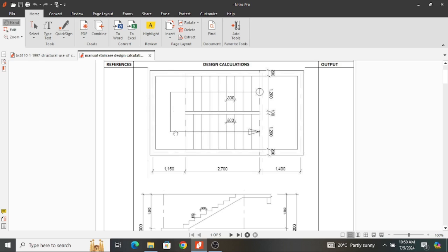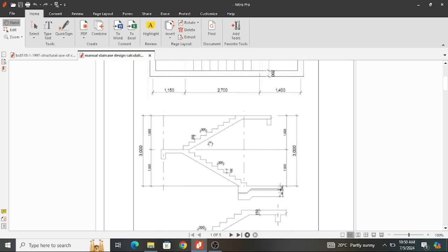And then for this one, it also distributes some loading to this axis, and sometimes probably at this section it could be cantilevered. So you are still going to distribute it to this side and then this load you still distribute along this axis. But just consider the supports you have, they are the ones to guide you on how to distribute your load.